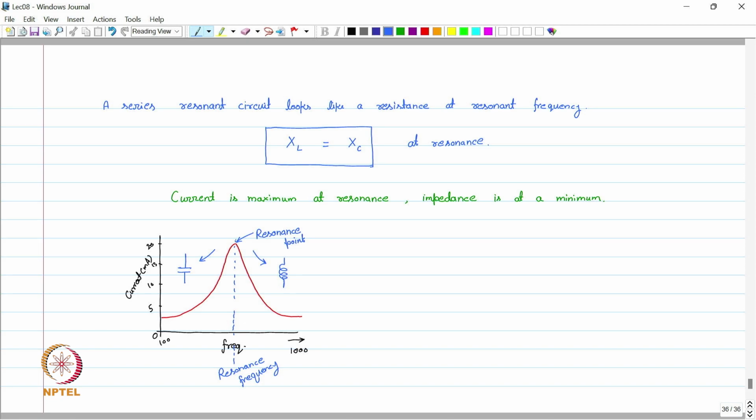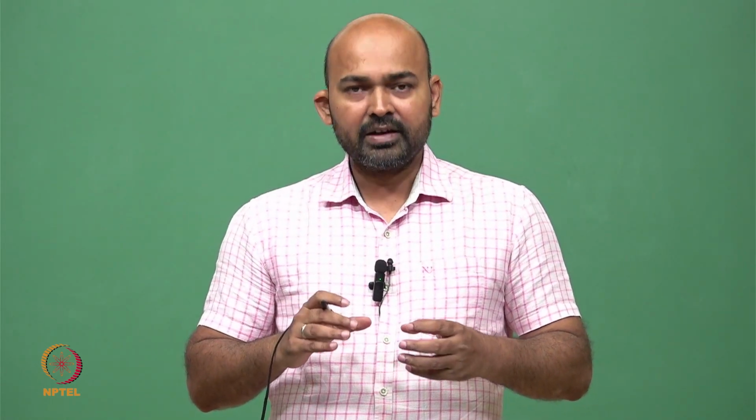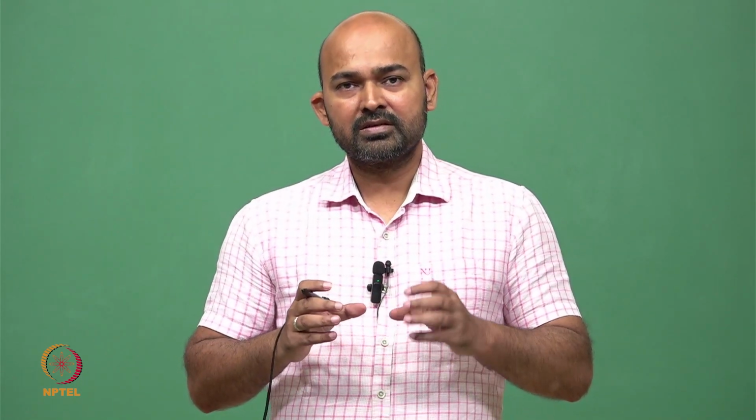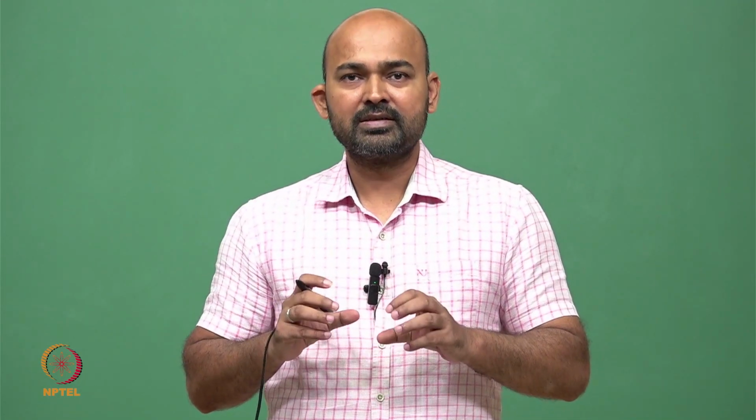And at this particular resonant point, the capacitor and inductor values cancel out each other, and the net impedance looking into this series resonant circuit is totally resistive.